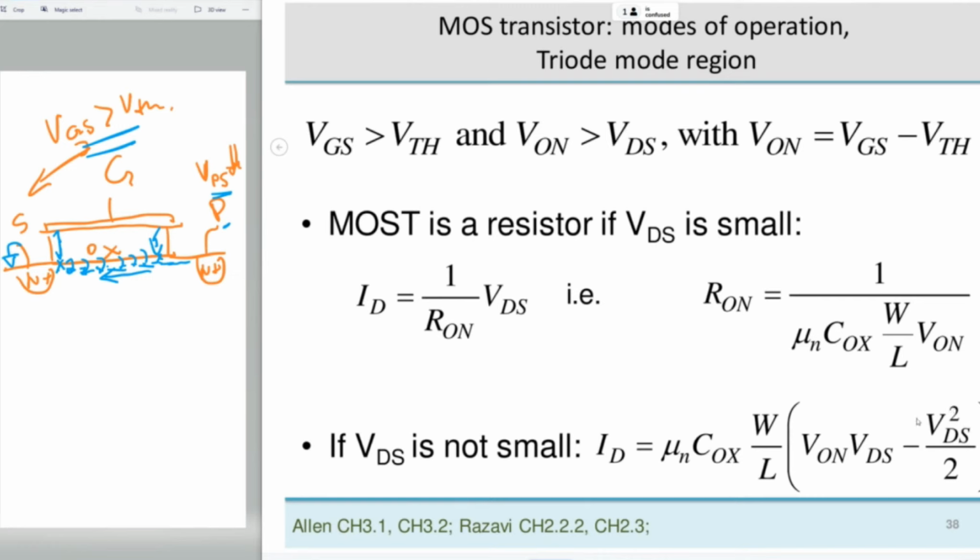Yeah, and then you can define this as G, conductance, and then G is 1 over R_ohm. Then you can define the ohmic resistance. This will be the resistance of this channel, and then the resistance, you can express it from here to be equal to this. And of course, if you increase the size of the transistor, it's like putting resistances in parallel. So the total resistance will drop. If you increase the L, the total resistance will increase.